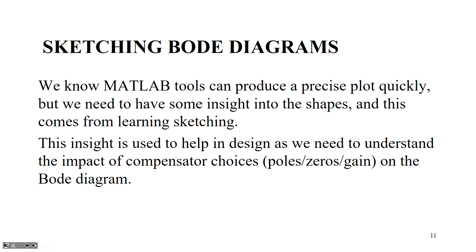Sketching Bode diagrams. Now we know MATLAB tools can produce a precise plot fairly quickly, but we want to do sketching because it gives us insight. And that's why the rest of this video is focusing on how you might do sketching. And once you understand that, you will be able to understand the impact of compensator choices, such as where you put the poles, where you put the zeros, where you put the gain, on the Bode diagram of the compensated system. And that insight will help you when you need to do design.